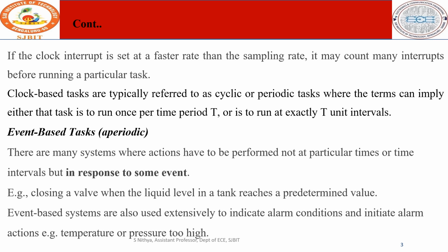And when we come to the event-based task, it is also called an aperiodic task. It will not perform in a specified time interval. Whenever the event occurs, that time the operation takes place. That's why it is called the event-based task, and also aperiodic. It is not periodic; it is a non-deterministic workload model. The classic clock based model is a deterministic workload model, but the event based task is a non-deterministic workload model.